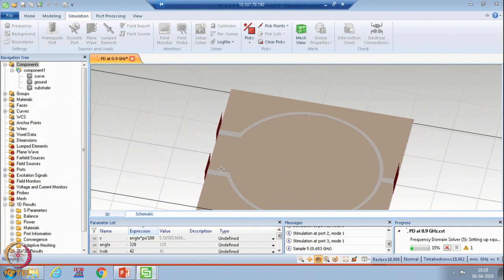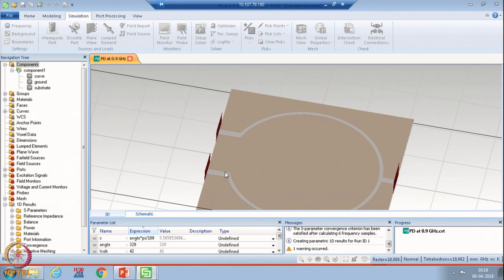The value of the resistor should be 100 ohm. Since we are working at 900 megahertz, we will use the SMD resistor, and the size of the SMD resistor is very small. So, in our case we will be using 0603 SMD resistor. So, we should make the pads accordingly.